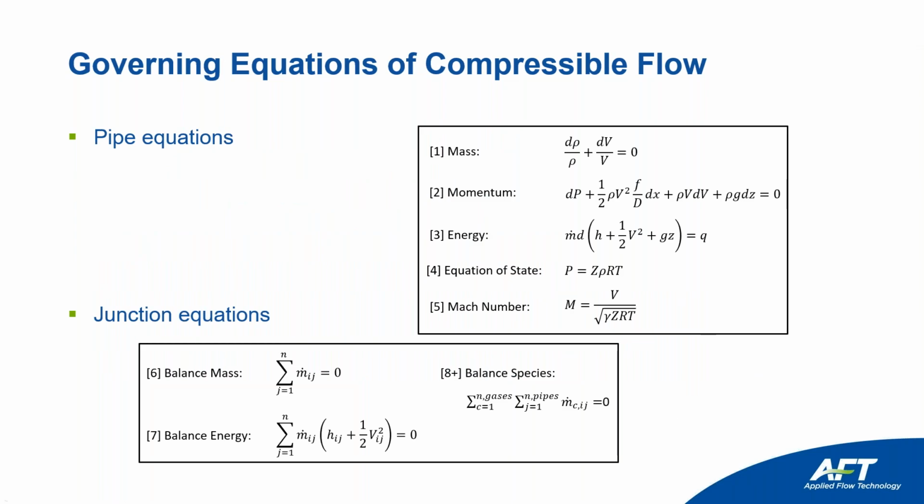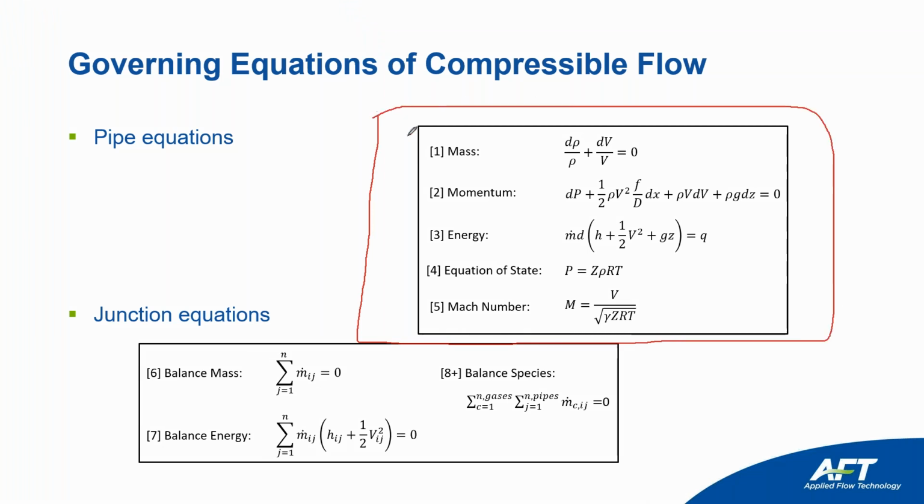These are the five fundamental equations that are being solved in every pipe throughout the piping network: the mass balance, momentum balance, energy balance, equation of state, and Mach number. These are the fundamental equations solved inside the pipes.